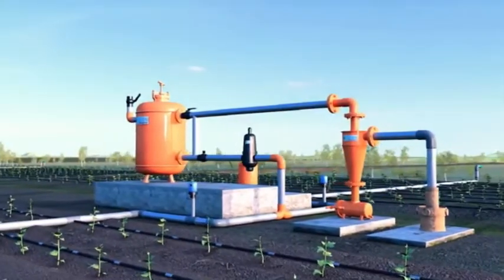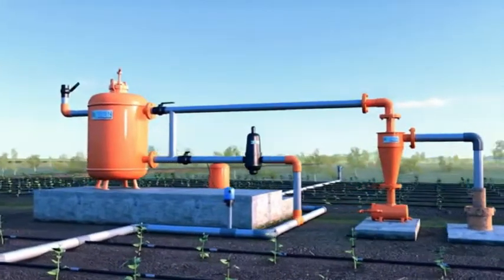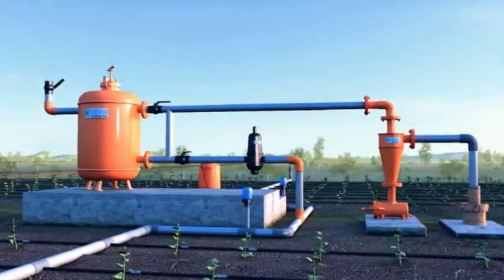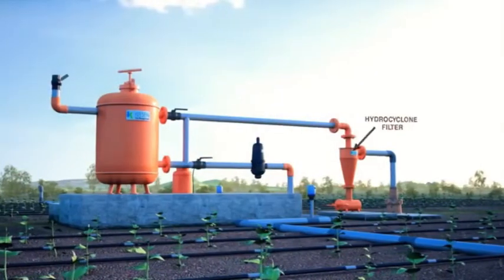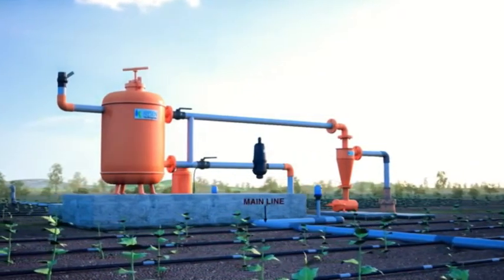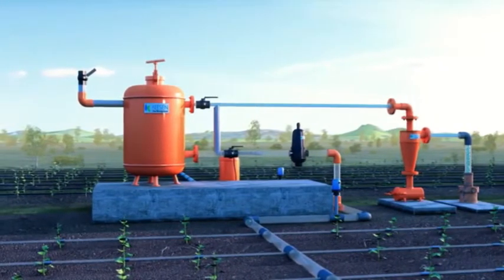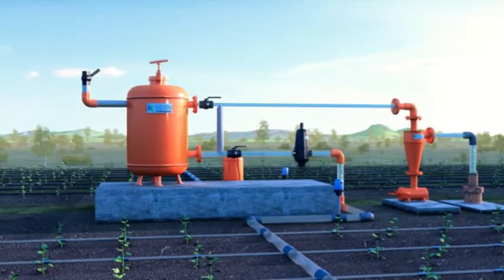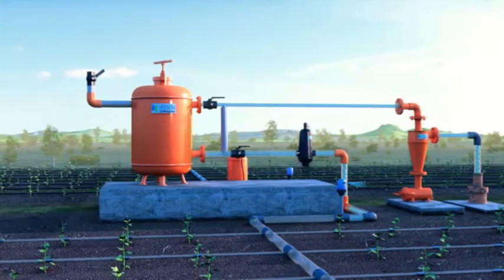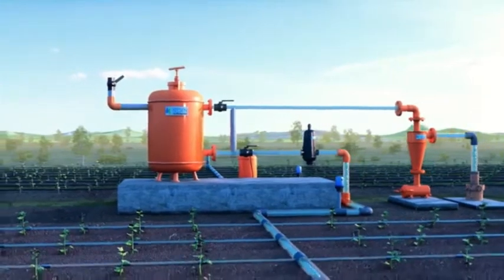The disadvantage of the drip distribution system is that it requires a large dose tank after the septic tank to accommodate the timed dose delivery of wastewater to the drip absorption area. Additional components such as electrical power are necessary for this system, requiring an added expense and increased maintenance.